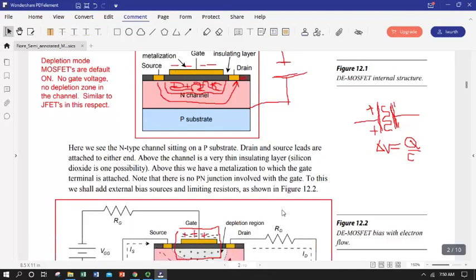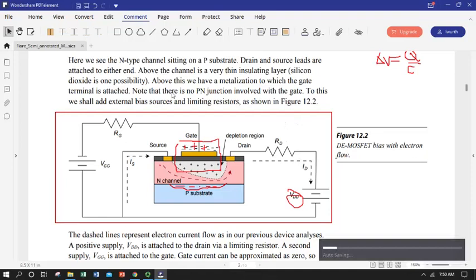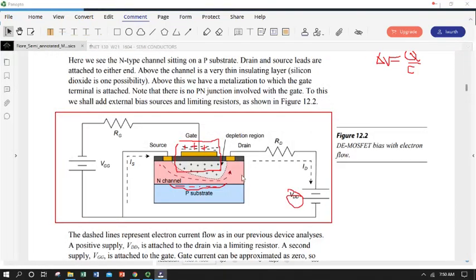If you are building them in your circuit, always try to make sure you don't allow charge to build up. Generally speaking, that's going to involve using what's known as electrostatic discharge grounding and clothing. You obviously don't want to necessarily ground yourself when working with electronics, depending on how you're doing your safety. Generally, you want your circuit grounded and not you. You certainly don't want a voltage source finding an easy current path to ground through you, but you can allow enough conductivity through your fingers to bleed off that very small amount of electrostatic charge.